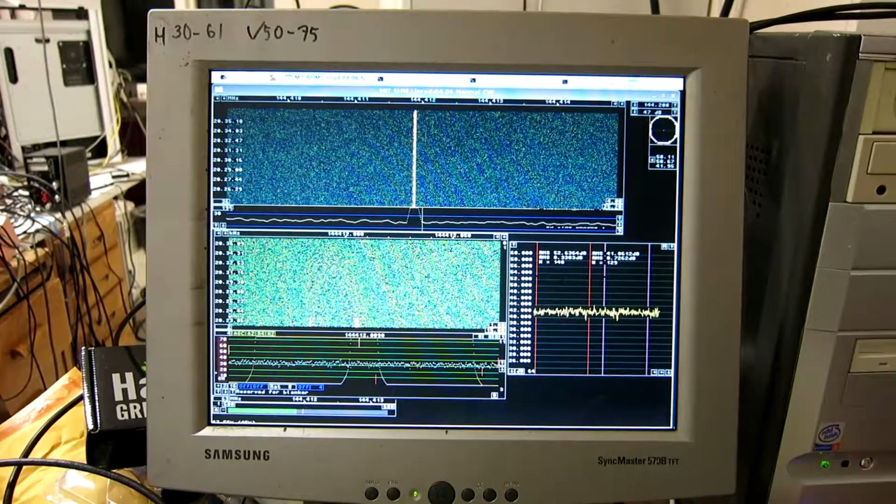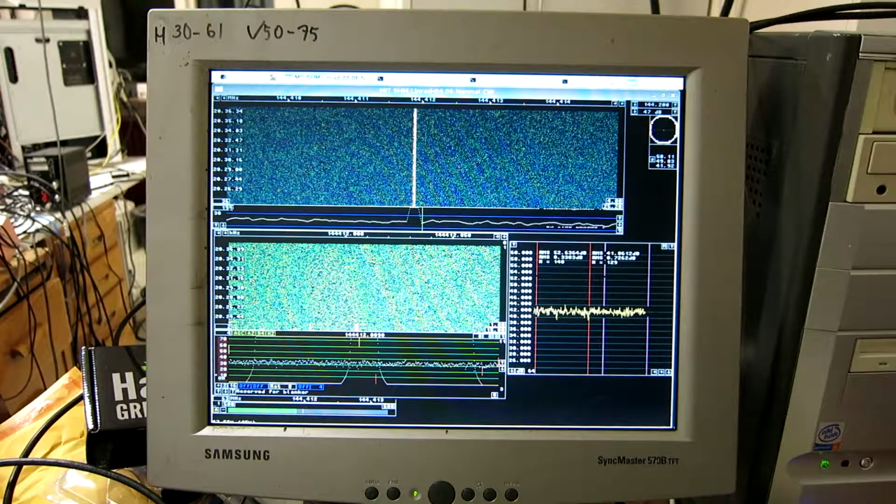To put it in perspective, the noise floor in SSB bandwidth 2.4 kHz is minus 140 dBm. The weakest signal detected with JT65 is 28 decibels below that. But the limit we have seen here is 44 decibels below that, which means the signal is about 16 decibels below the detect threshold for JT65 in deep search mode. So it's a really weak signal.